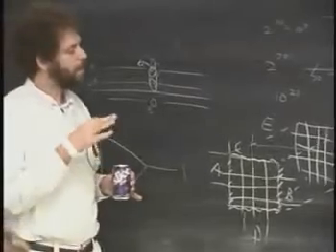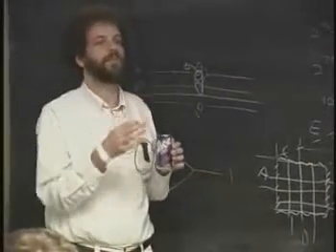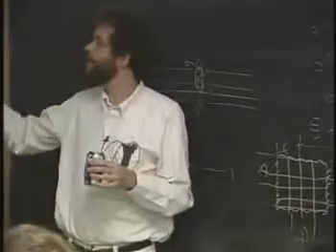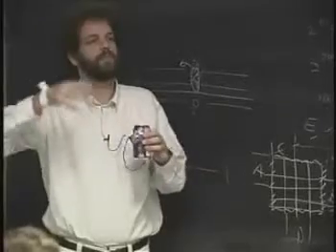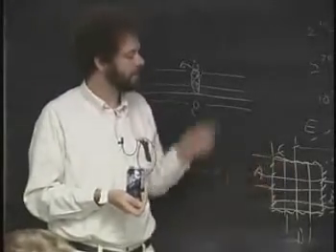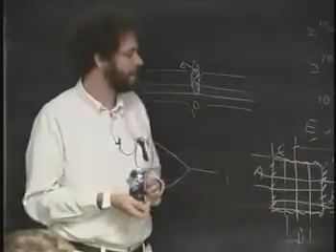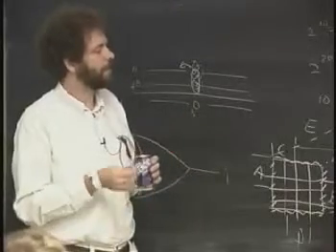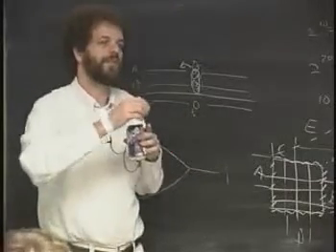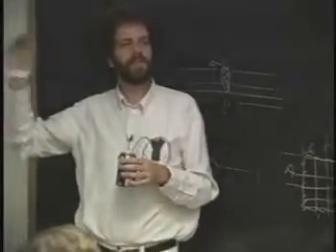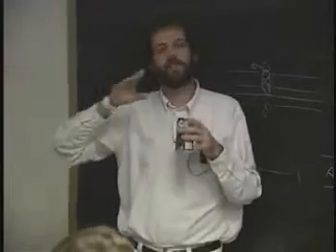What's actually going on is that all of these things are really what's called a hypercube, a binary cube that is going into more and more dimensions, and each time we add another input to this thing, we make the cube bigger and bigger. The only difference is that we've managed to get away with doing 4 things in a plane just because in our minds we can say this surface is the same as that one. But to really do it right, you just have to think that every time you add another bit of input, you add another dimension to this hypercube. And the software programs that do all this work for you in a split second do it in that fashion. The software thinks of these things in terms of a hypercube.